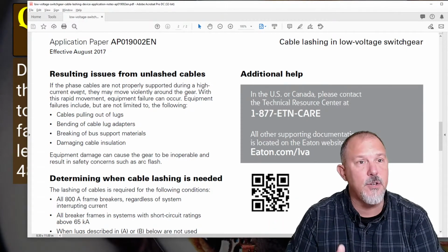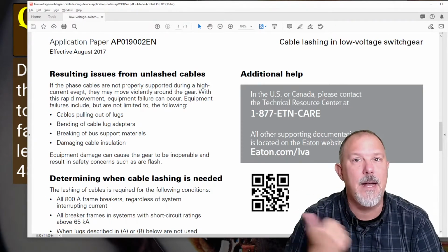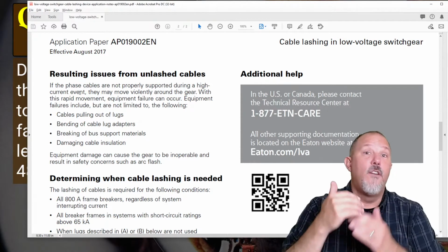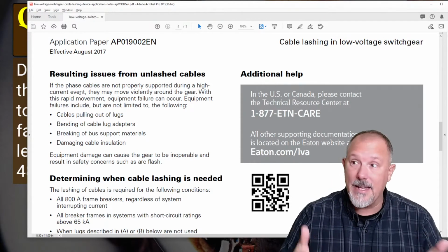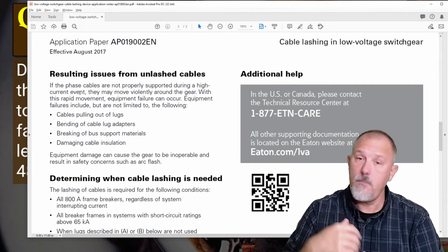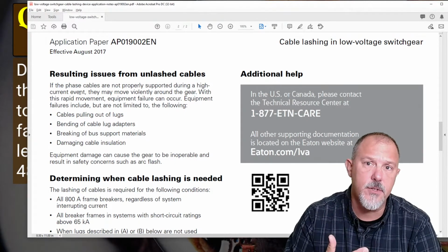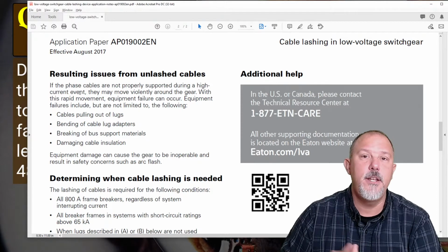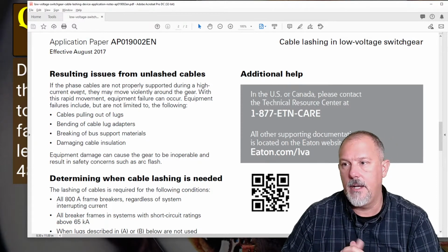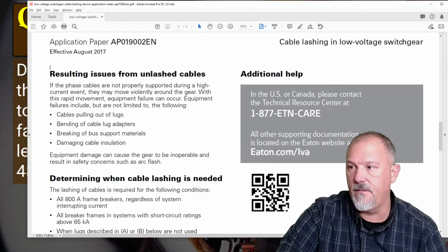But on my circuit breakers, I'm pushing the instantaneous way out there to the right, and I'm adding an intentional delay. For fault currents passing through the equipment, that's a lot of magnetic forces that I'm going to be permitting for downstream faults. Lashing your cables is a very well recommended thing to do because of those magnetic forces.